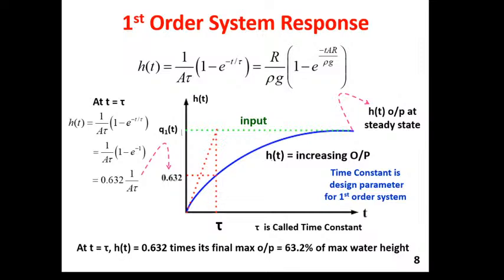So if you see that there is a certain point towards the top of the blue graph where the blue line is touching the green line and staying along with the green line, that means the output has got saturated and the height of the liquid inside the bucket or container has become constant, and Q1 minus Q2 is constant, constant inlet and constant outlet, and H is a constant term. Okay, so that's why it is said by the pink line that HT is the output at steady state. That means with Q1T input and Q2T outlet, the liquid level is not going up anymore.